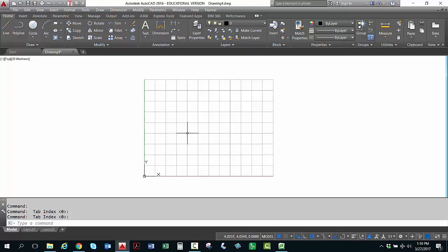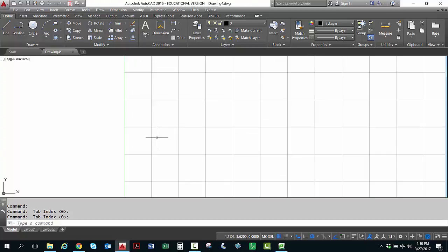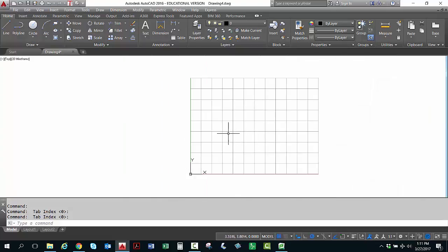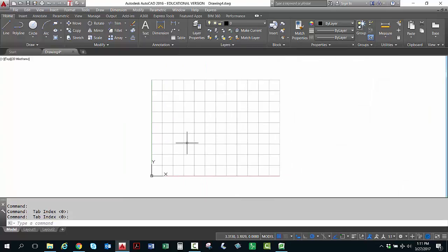So if this is an inch, then every grid spacing you see here, alright, this is 0.5, 0.5. So really that's at 2, isn't it? So the major grid is at 2 inches or 2 units. Alright, then we go and we set up our layers. I'm going to pause for a moment and set those up. That's on page 7-9.